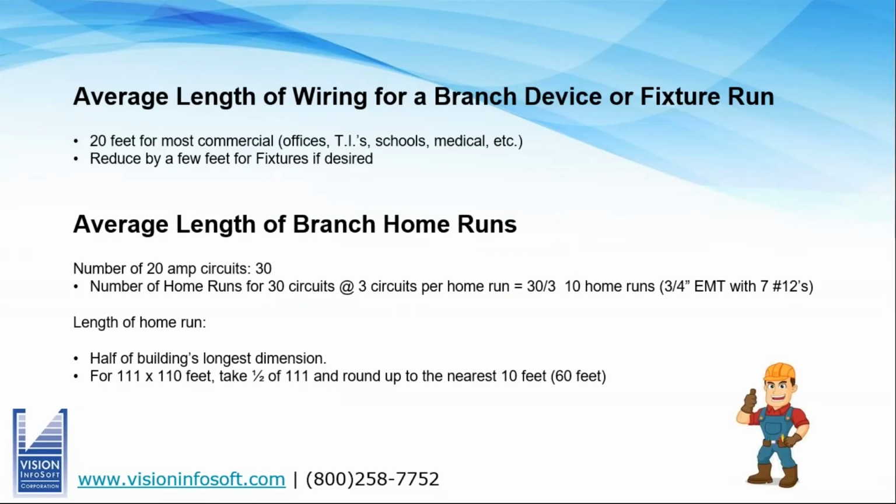For typical commercial jobs, now again, we have to define typical, it doesn't mean any kind of job. You can't look at a 10,000 square foot warehouse with 2 lights and 2 receptacles and use these kinds of averages. But for a typical commercial building, offices, tenant improvements, schools, medical, etc., you're typically going to find that a 20-foot average per device per fixture is actually going to be on the conservative side.